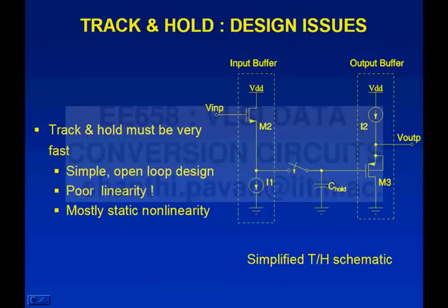It makes sense for voltage swing reasons to use one buffer which is an NMOS buffer, another buffer which is PMOS, and it makes sense to use a PMOS buffer which follows the hold capacitor rather than the other way around, because we know that in practice a lot of technologies are so-called N-well CMOS technologies where you don't have access to the body terminal of the NMOS transistor. It is naturally grounded, which means that the incremental gain from here to here is smaller than 1.